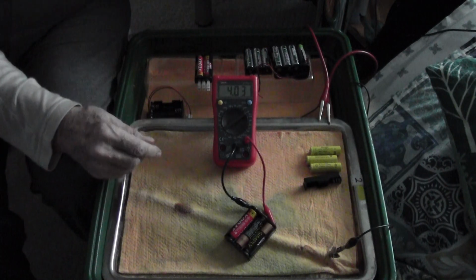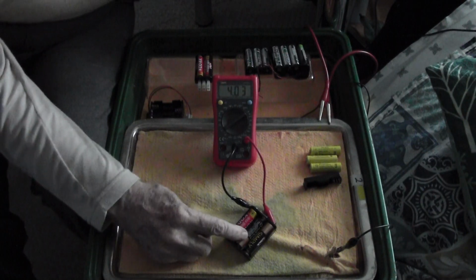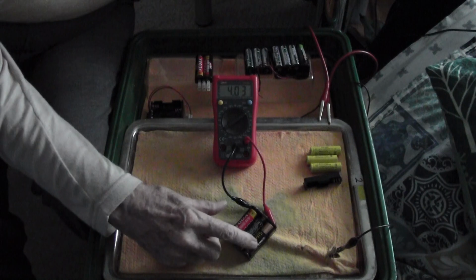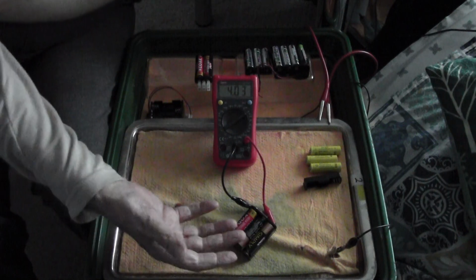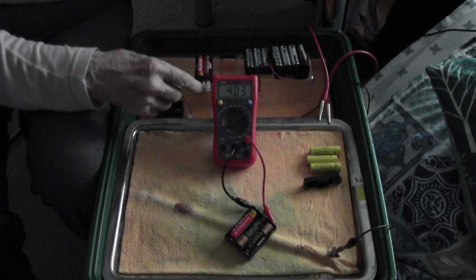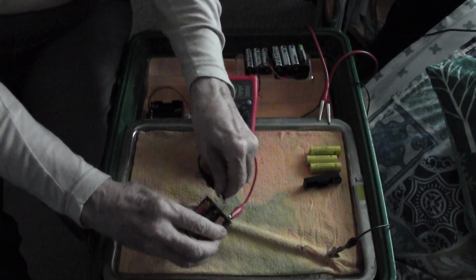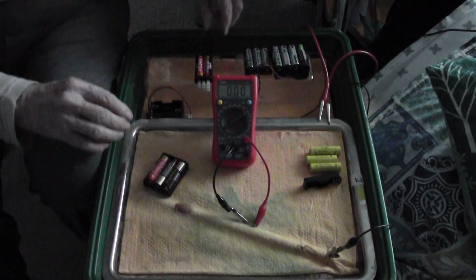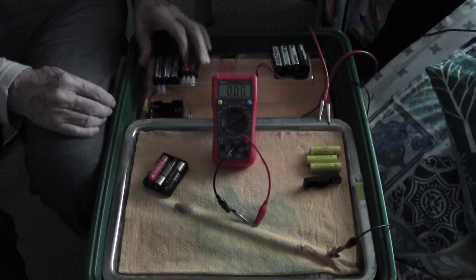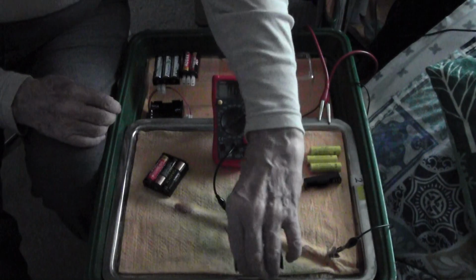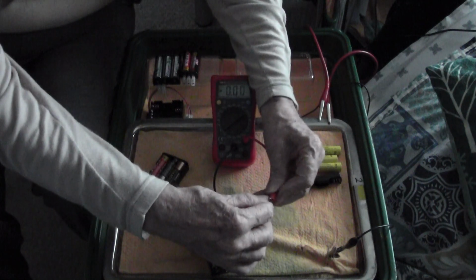Now, if you think that this represents the corrosion on the pipeline, this represents the telluric effect, and this represents the half-cell reaction itself, how can we analyse that reading? We can't. Okay? Now it gets even worse, because as the sketch showed you, there are more often than not a lot more influences, and some of them are fluctuating.